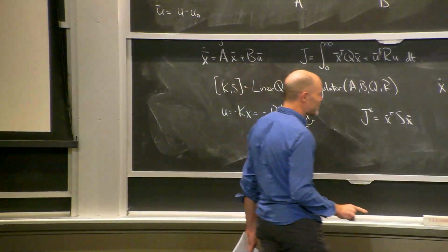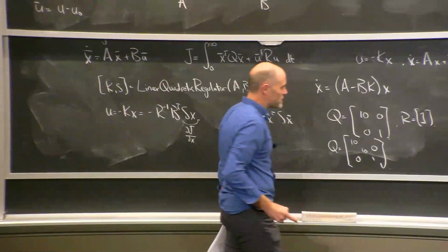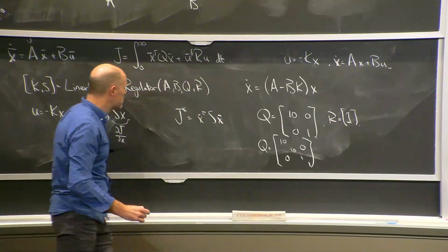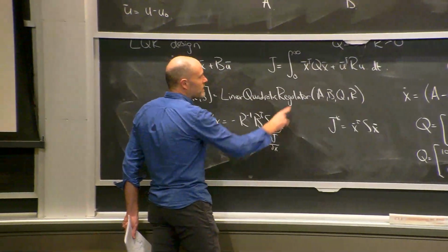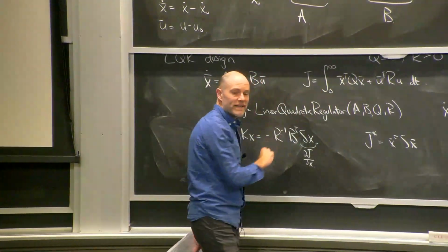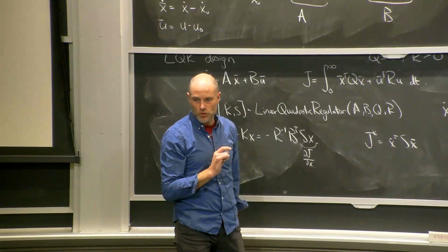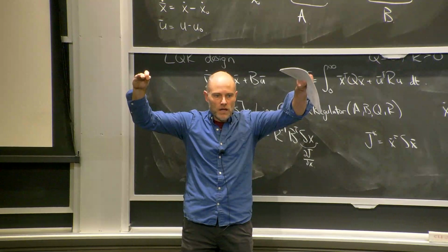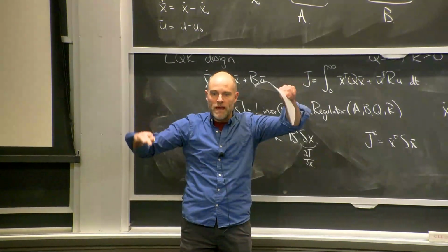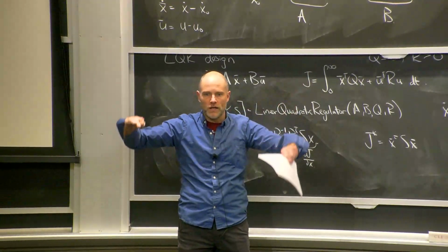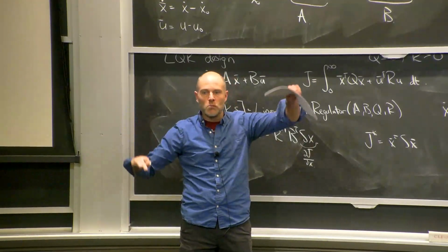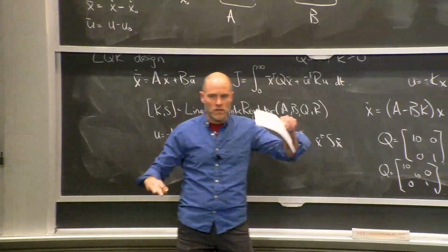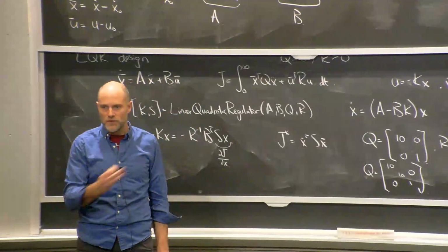So we can think about that. If I increased both Q and R, if I just multiplied this and this by 2, then that would just be a multiple of my cost. That wouldn't change my optimal controller. So if I move both Q and R up and down together, then that doesn't matter. What matters is the Q versus the R. How much do you care about getting to the origin versus using too much effort? So there's a scaling there that you just don't have to worry about. Just pick R to be 1, and then just mess with Q.